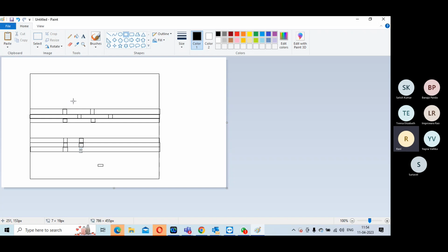The other end cap cell will have internal tap, or will have continuity. So these are all things that are there to decouple the external noise from the internal of the block. Because you are closing internally, but this wire will get a coupling noise effect if you don't add end cap. Other than the tap issue, other than the buffering issue, these are all things. So end cap is a special cell which will take care of 2-3 types of requirements. You understand?